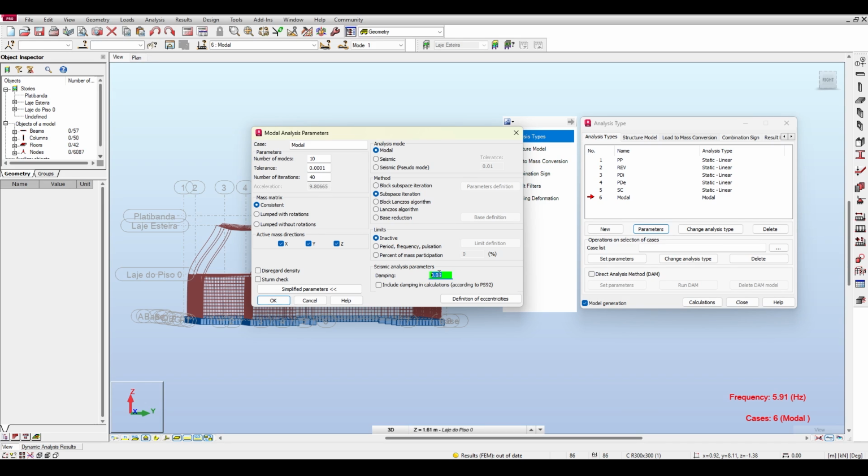Now relax. The difference between an undamped and a damped frequency is not going to be that much. You can check out the dynamics books for this. Of course, I'm talking about damping in the normal regions, not super damped or like 50% damping. I'm talking about the regular ranges of damping. The regular ranges of damping for steel structures are not going to have an effect on modes. For concrete structures, it may have an effect. So please check out your references for more.